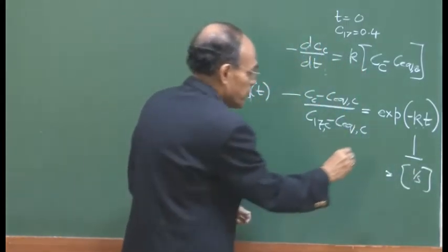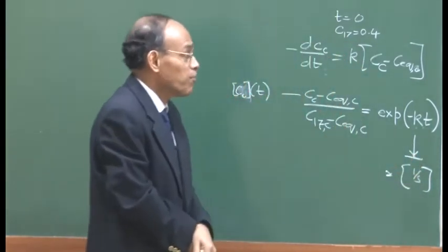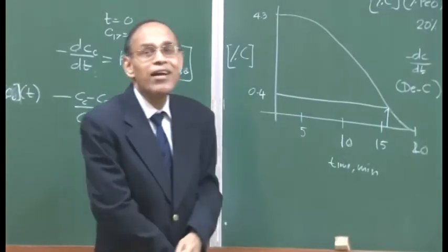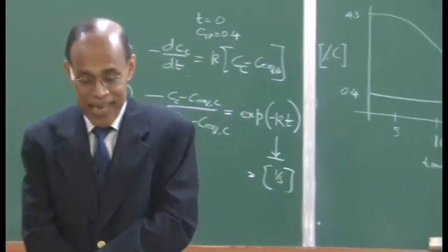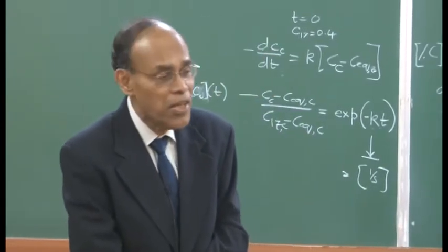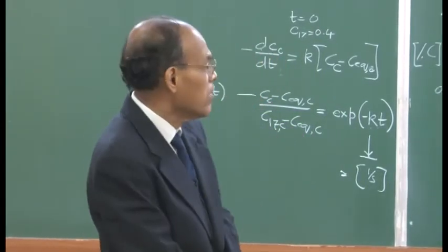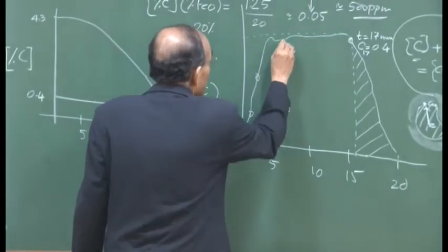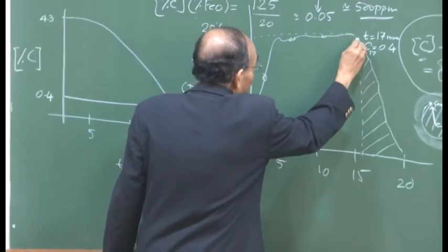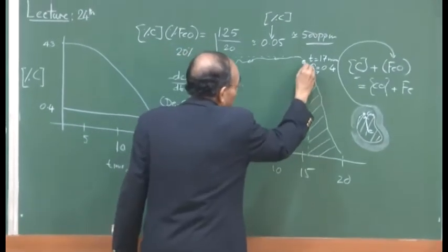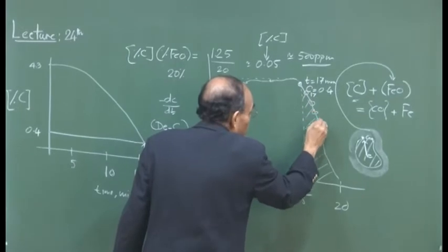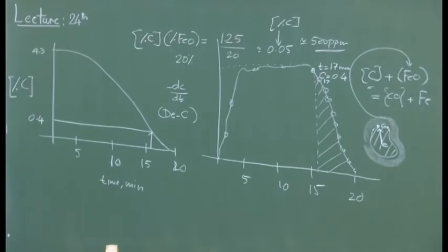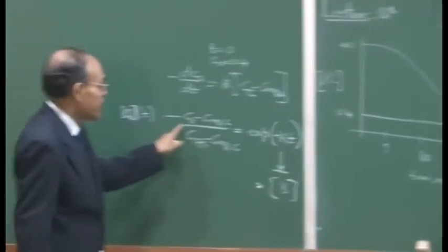and this needs to be specifically determined, and to determine that you have to take samples. These are very difficult experiments on an industrial scale. You are talking about 1600 degrees centigrade, you are talking about taking innumerable samples right from the beginning. You may not take too many samples here, you may take only a few samples, but identification of this point is very important, and from here you require a large number of points, so that you should be able to determine your rate constant.